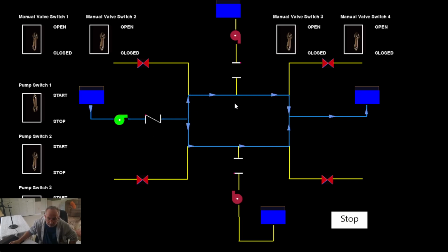from this particular pump, because each of the check valves for the pumps that are not working are closed, preventing any more fluid traveling through the lines through to the tank. So, if, for instance, I open up this valve, which is valve number 1, then you can see the flow of fluid traveling through the manual valve out to atmosphere. This is the only pump that's operating.